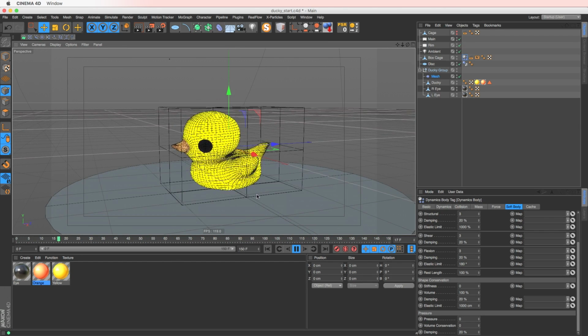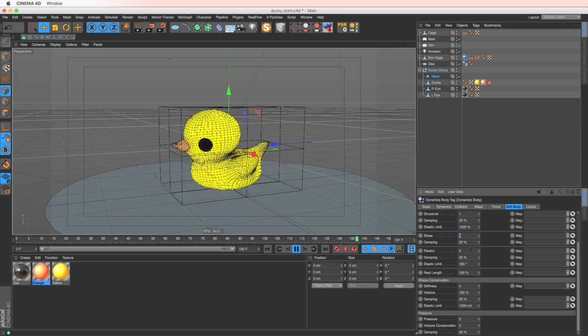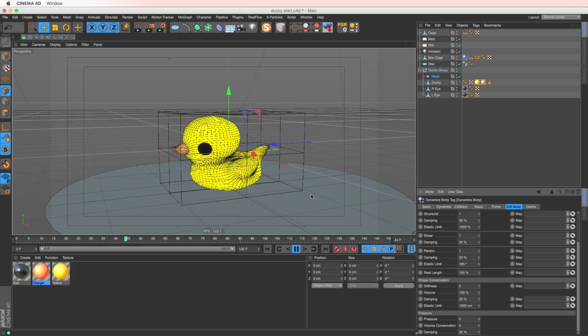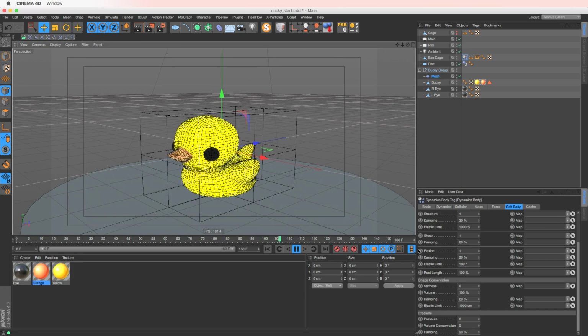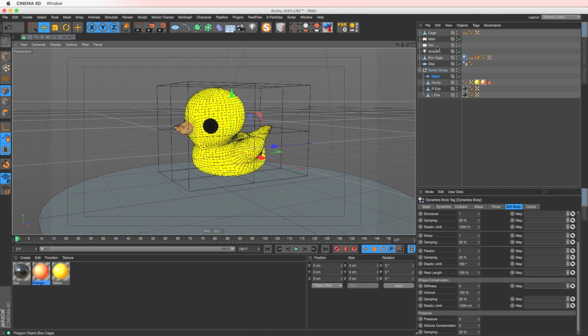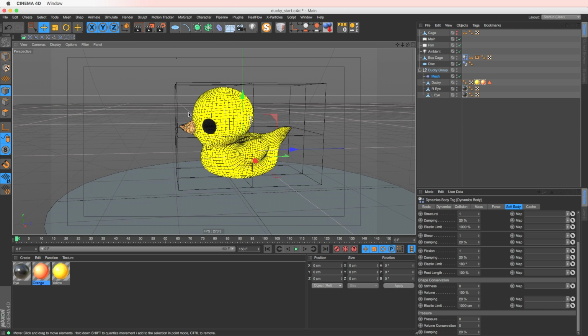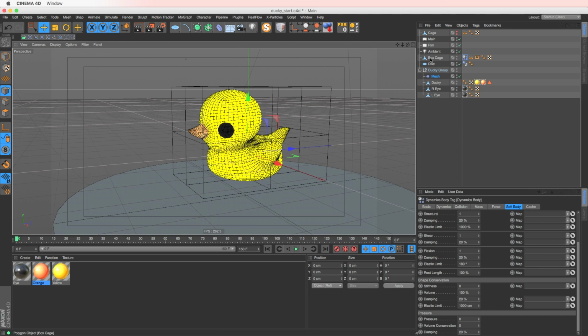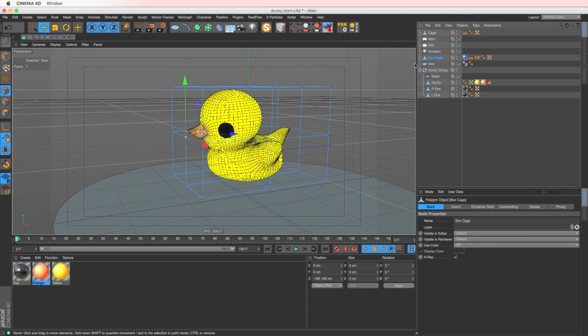So unless it's just quick and dirty and you just really want to make this really bouncy, bring the structural really low. Maybe that's good enough. Maybe this isn't colliding into anything else. Having this low poly box is perfect. But if this is colliding into something else and you need to recognize some of these contours of this shape, what you would do is some box modeling basically.